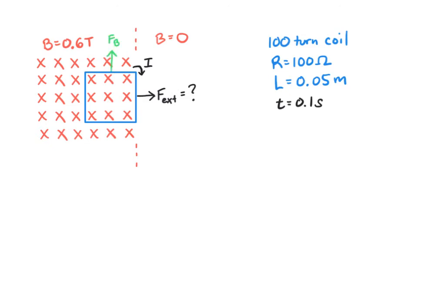But along the bottom, the current is going the other direction, it's going to the left. And so if we use our right hand rule again, this time we find that the magnetic force on the bottom section is pointing downwards. And since each side of this coil has an equal length and the current through each side is the same, these forces are going to be opposite. So unless they're strong enough to literally tear our coil apart, we can ignore them. They're going to balance each other out. That leaves just the leftmost side of our coil. The current is going upwards along there, so if we use our right hand rule, our fingers point up and then turn into the screen in the direction of the magnetic field, we find that our thumb points left and the magnetic force on the left side of the coil is pointing to the left.